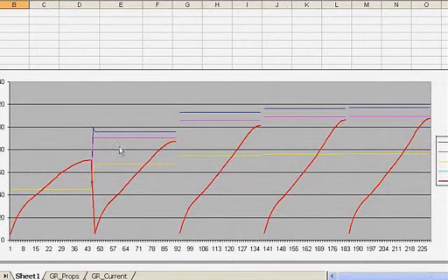And you can see the 5 stages of the program. Here's stage 1, stage 2, stage 3, stage 4, stage 5, and the temperature is converging to a steady state. In the temperature model, I had convection and radiation on the external surfaces of the ferrite. So when the internally generated losses equal the cooling, then the device will approach a constant temperature.